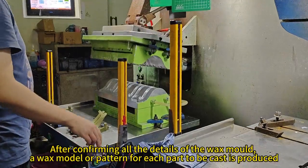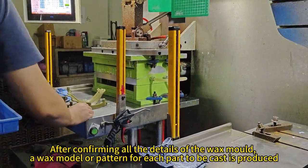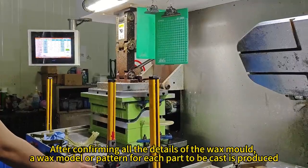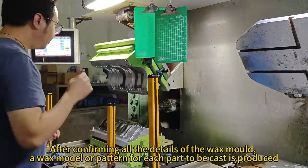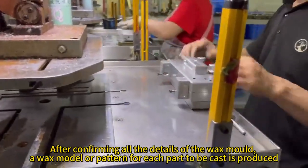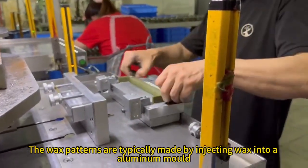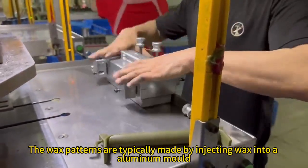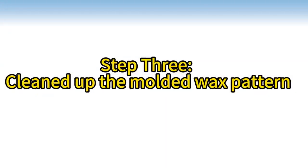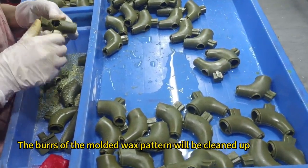After confirming all the details of the wax mold, a wax model or pattern for each part to be cast is produced. The wax patterns are typically made by injecting wax into an aluminum mold. Step 3. Clean up the molded wax pattern. The burrs of the molded wax pattern will be cleaned up.